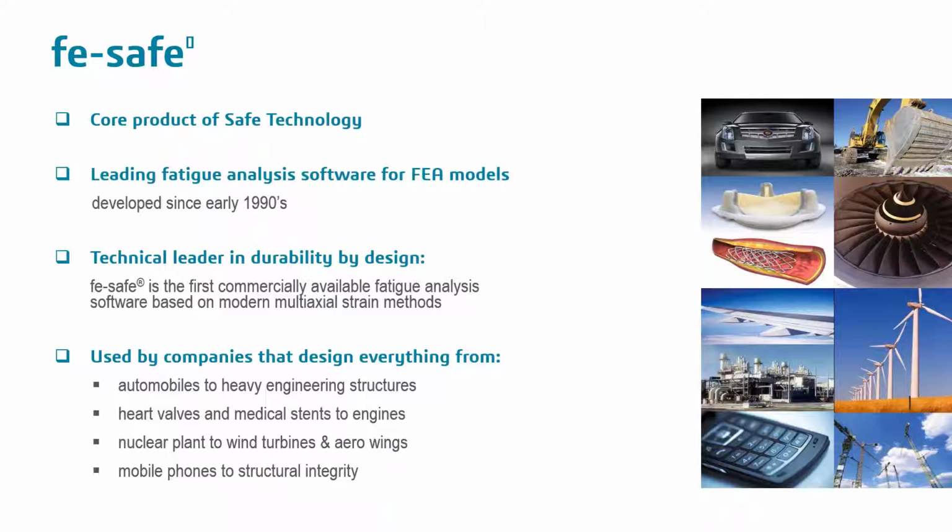FE-Safe will be able to read the stress results and potentially multiply that with some signal data, or in other circumstances, the FE simulation upstream could actually contain a more representative reflection of the product's operating conditions, maybe a rotating object or thermal cycles, for example, that could be imported as such.